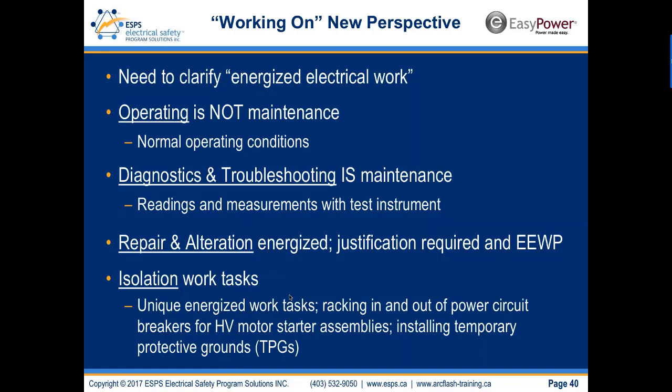Diagnostics and troubleshooting is maintenance. Repair and alteration, again, energized, justified, requiring an energized electrical work permit, is going to expose a worker to arc flash and shock. And I broke out isolation. So isolation work tasks are racking in or out power circuit breakers or high voltage motor starter assemblies, or installing temporary protective grounds. Those are not maintenance work tasks. Those are isolation work tasks.